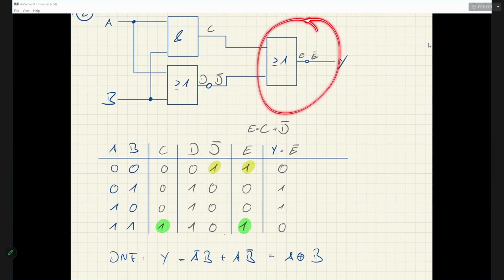For the NOR gate to produce an output of 1, both inputs have to be 0, right? So that means the output of the AND gate and the first NOR gate has to be 0, right? Sorry, again. Yeah, the output of the first two gates there, the AND gate and the NOR gate, their output has to be 0 for the final output to be 1, right?